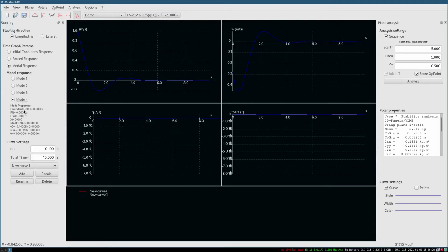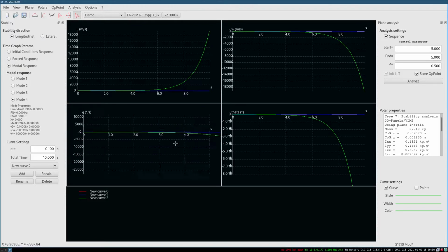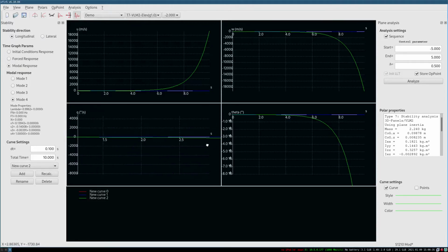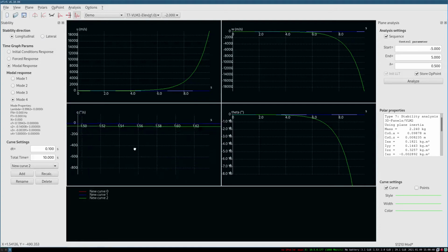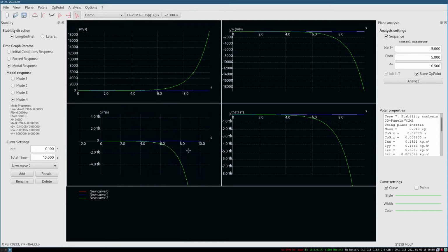And then you have this stuff that is at a plus value, and this stuff does not damp out. This stuff, you have about 4 seconds to catch it. After these 4 seconds, you find that things very quickly fall out of hand. I mean, within 4 seconds, yeah, we're talking quite big disturbances. So really, you've got a second or two to catch this sort of thing. That's definitely on the short side, but that's something that if you had a prototype aircraft that you were flying in a matter of hours, you could definitely brief the pilot about and be aware of.